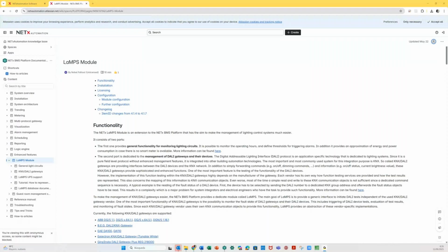When you have a DALI sensor, it is just for lighting, but a KNX sensor could have different layers, different channels, and you can use it for lighting, for HVAC, for security, or whatever. So normally in the projects, integrators are still using KNX sensors, KNX push buttons, touch screens or whatever, and DALI is just for drivers, for ballasts.